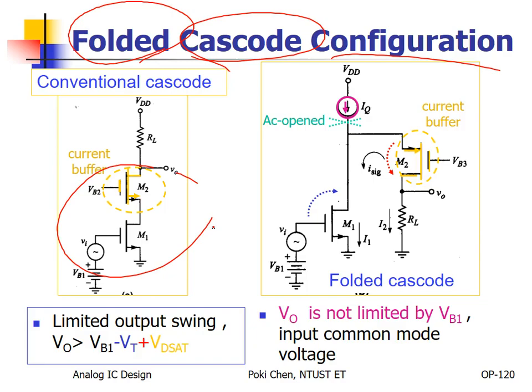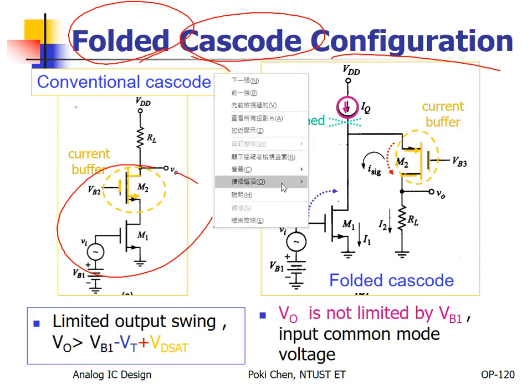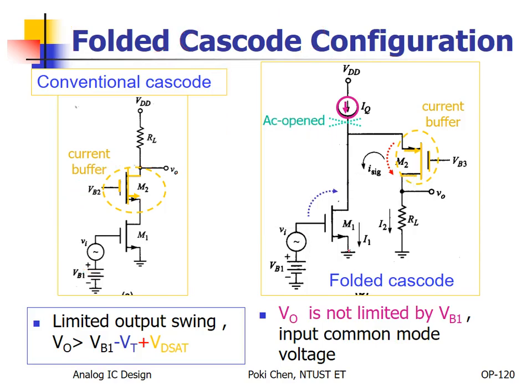But we need to go further. Go to the bottom. What is the function of cascade? Again, the cascade transistor needs to be a current buffer, right? The major purpose is to deliver its input current 100% to the output, but increase the output resistance.